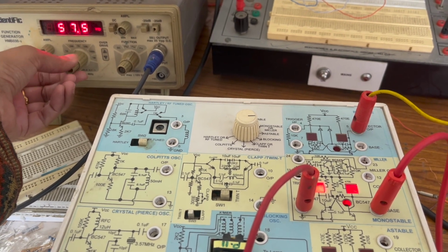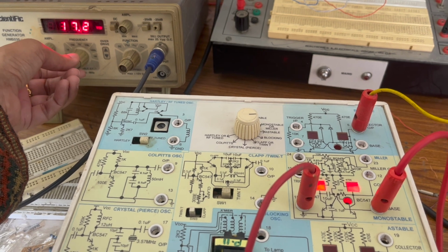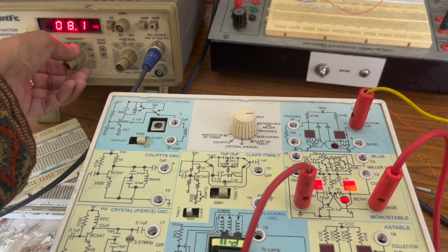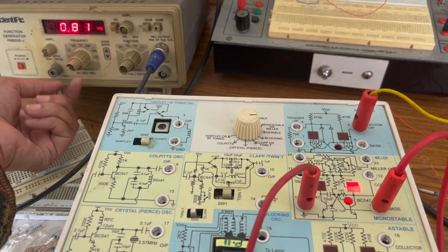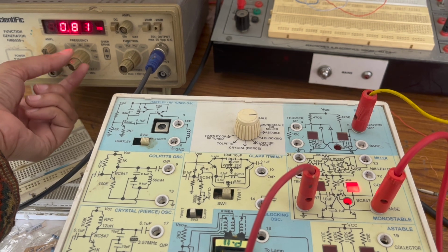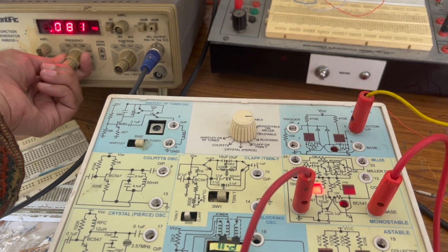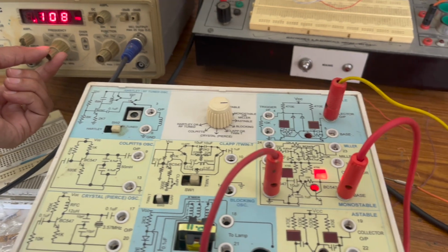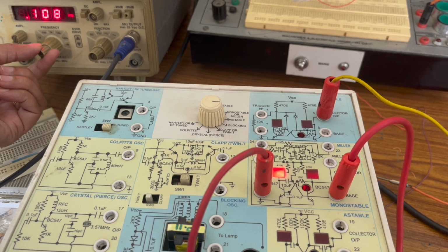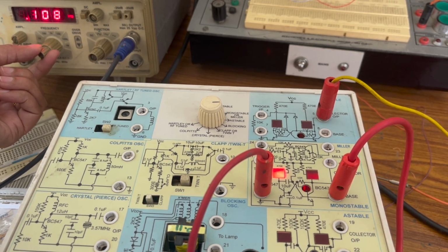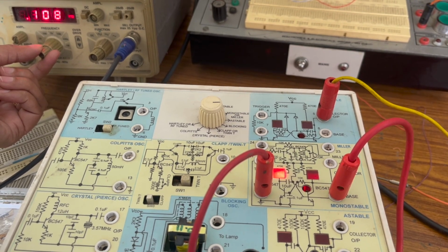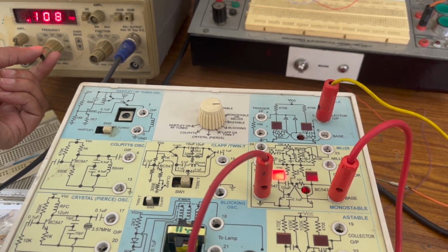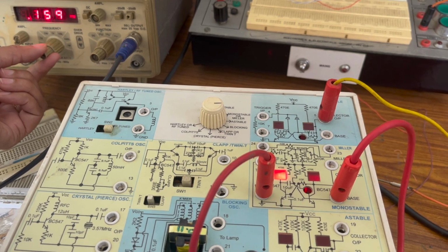Let us reduce the switching frequency and you can observe. As you reduce it, the switching will reduce. See, it is 0.8 Hertz. So, it goes to quasi-stable state, comes back, again goes to quasi-stable state, and it is at the stable state now. This is the quasi-stable state and this is the stable state. It automatically comes back to stable state. Again it will go to quasi-stable and it will come back to stable state. That is how monostable multivibrator works.